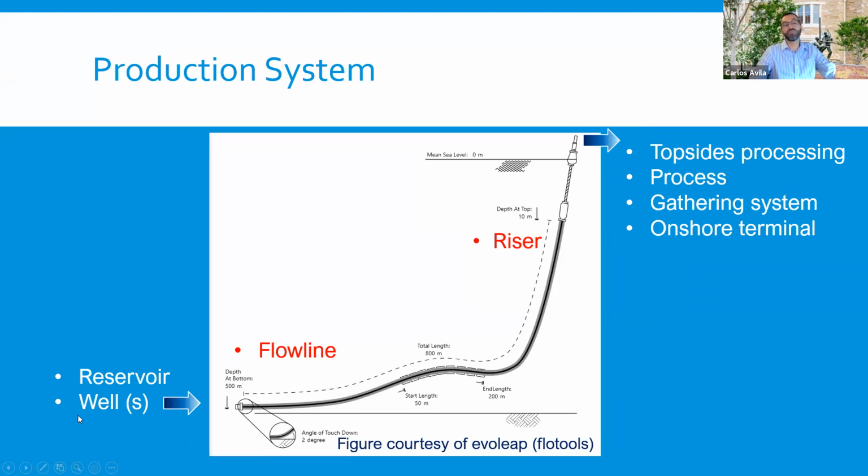But anyway, the transport of these fluids from the reservoir all the way to the processing facilities has many challenges along the way. As the fluids flow out of the reservoir at high pressure and higher temperatures, they have to overcome pressure drops through the flow line, changes in geometry and inclination angle, and steep risers. Also, don't forget that this flow line is on the seafloor, where the seawater is significantly colder. So there's a temperature gradient between the fluids being transported and the wall of the flow line, and all this change occurring in a complex fluid such as a crude oil may generate a chain of issues that you have to be aware of.